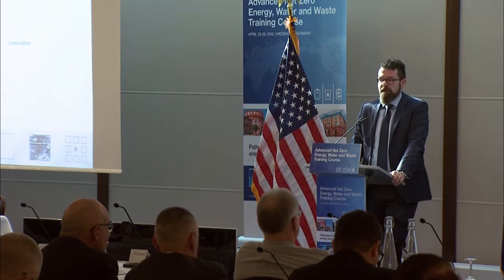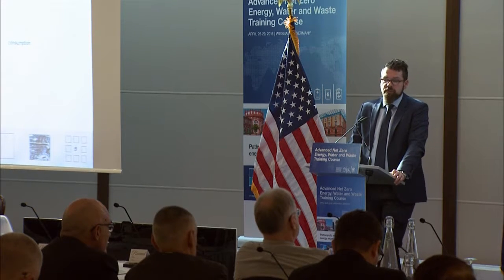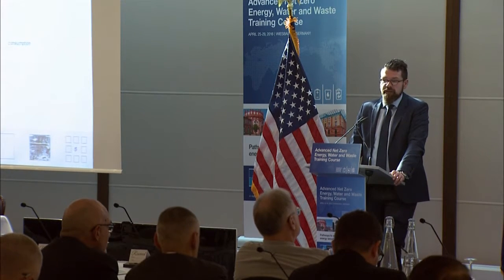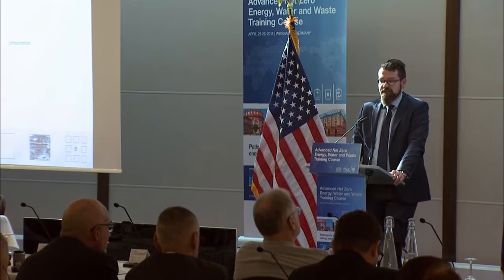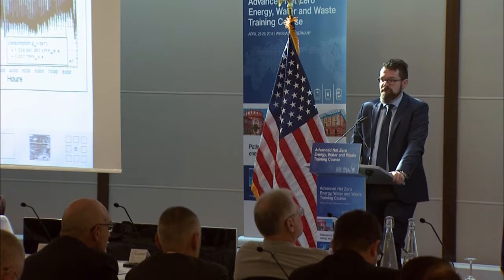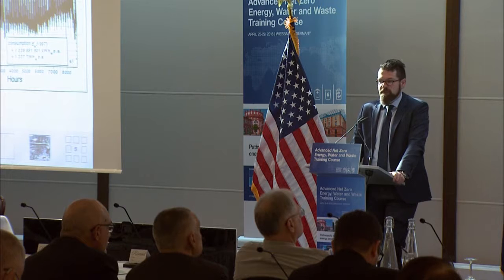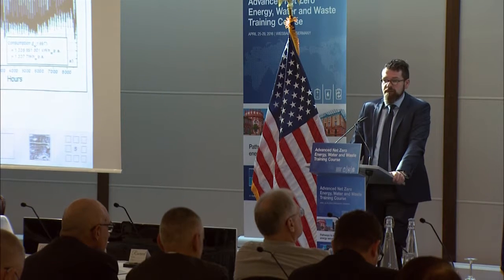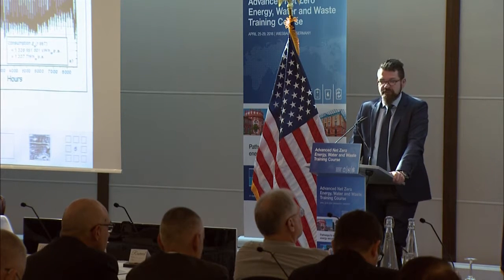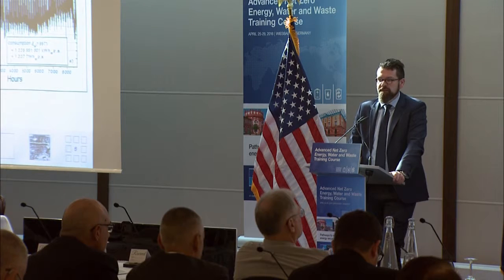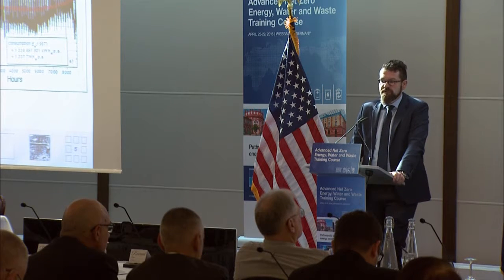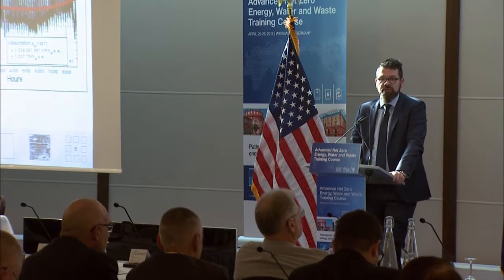If we have a look at that in total, you can see here an annual load curve for heating and an annual load curve for electricity. And if you look at it, you can see a main difference. In space heating and domestic hot water, we have a seasonal shape, and in electricity, we have almost no seasonal shape.